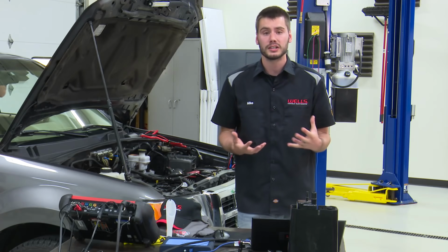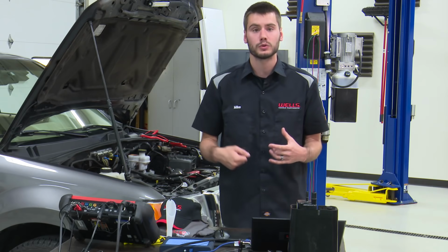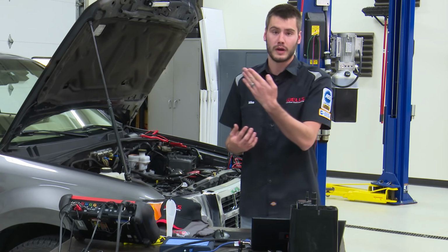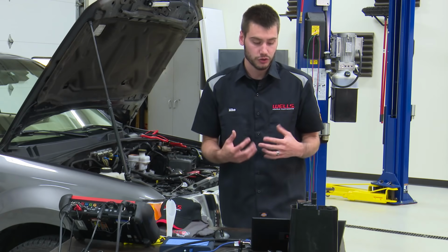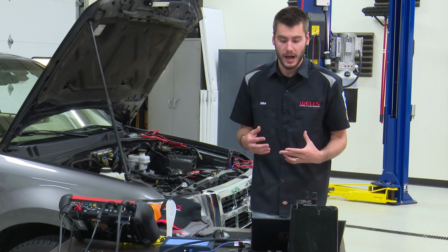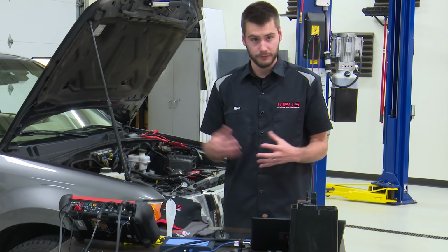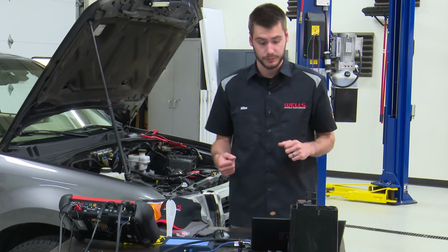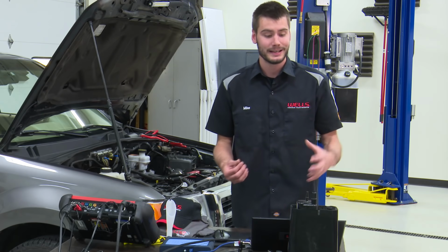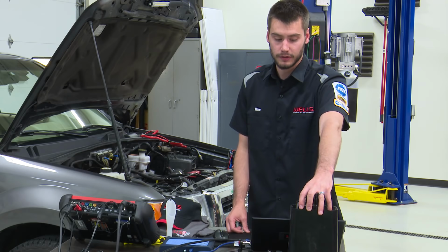Refueling was the largest polluter, and this started in the late 90s. Basically, we now have a 1-inch filler neck that when you're pumping fuel down it, there's not enough space. It creates a liquid seal and doesn't allow vapors to travel back up the neck. There's also usually some sort of refueling vent valve on the top that is going to allow the pressure buildup from dumping fuel into the system to be vented into the canister very quickly.